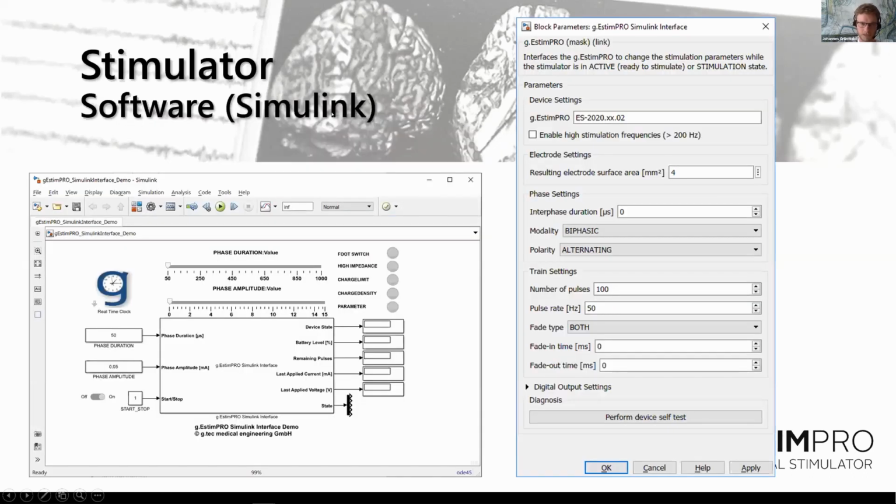Now, as I said, we also have a Simulink integration for the Estim Pro, which is shown here. We have a Simulink block. And when we double click this block, we have this mask with all the parameters we want to change. It's worthwhile mentioning that we can change most of the parameters while the model is running. So we don't have to stop the model, change the settings and start again. No, it can be done online. And this is what I meant with adaptive parameters previously.